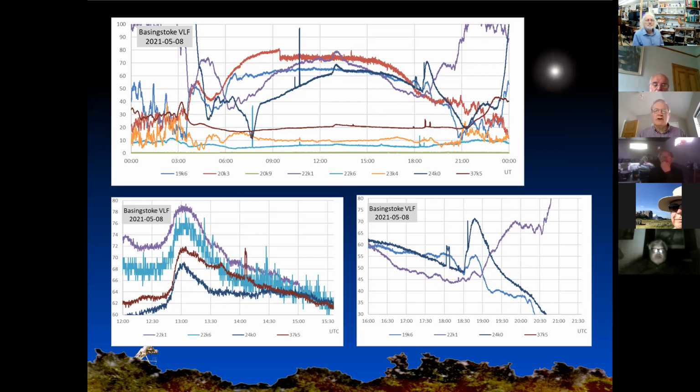The magnetic field is less susceptible to the vast amount of interference that's around at these low frequencies. So it's a magnetic loop antenna, and that is sensitive in one direction and not at 90 degrees to it. So when the frame of the loop is pointing at the transmitter, that's your maximum sensitivity. When the face of the loop is pointing at the transmitter, that's your minimum sensitivity.